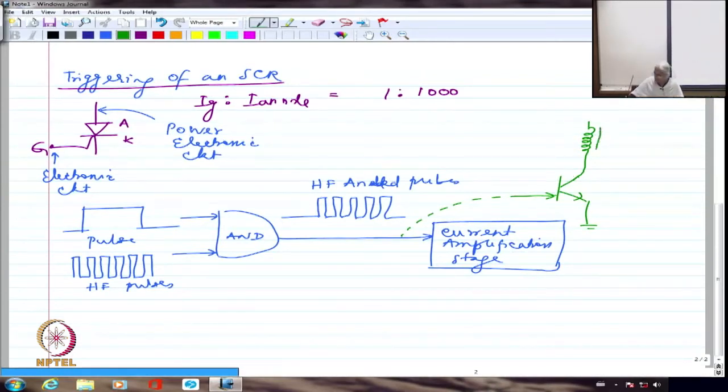The transformer primary I have shown, and I necessarily have to have another secondary. If we have seen big transformers in terms of megavolt ampere and so on, this will be 1 volt ampere or maybe a maximum of 10 volt ampere. That's it, nothing more than that. It is going to be a very, very small sized transformer. It will still be an iron core transformer normally. Generally the gate has to get positive and the cathode has to get negative when I am giving the gate pulses. So if I say that this is my VCC, which is plus, obviously this corresponds to minus.